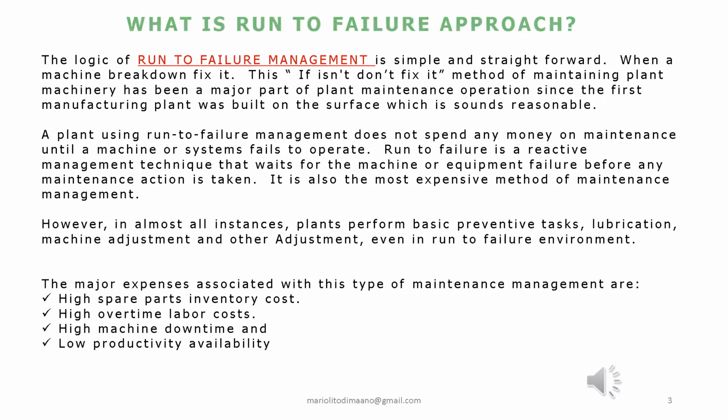Run-to-failure is a reactive management technique that waits for the machine or equipment failure before any maintenance action is taken. It is also the most expensive method of maintenance management. However, in almost all instances, plants perform basic preventive tasks, lubrication, machine adjustment and other adjustments, even in a run-to-failure environment.